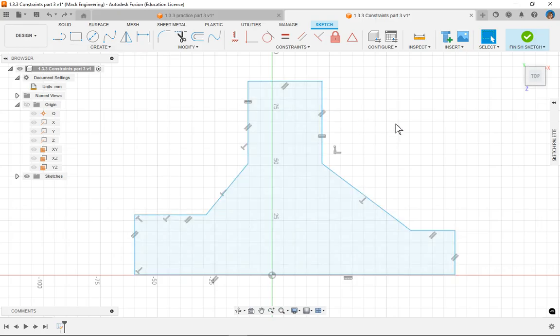Okay, so that's good. Now, there's one more thing that we want to make sure for the design intent on this. We want lines 3 and 9 to align horizontally so they move up and down together. So basically, we want them to share the same line. We want them to constantly move together. So the fact that I said horizontal, you're probably thinking we need to use the horizontal constraint. However, that will not work. And I'm going to show you here.